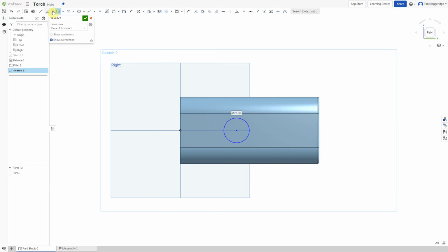And then I'm going to use a corner rectangle. So I'm going to pick the corner rectangle, I'm going to hover over the center of the circle, then go up. You hopefully can see dotted yellow lines. That'll tell me when I've picked up the 12 o'clock position on that circle, if you like. And then I'm just going to drag this out. Now I've dragged it out a little bit big on purpose because I want to show you a couple of other tools.